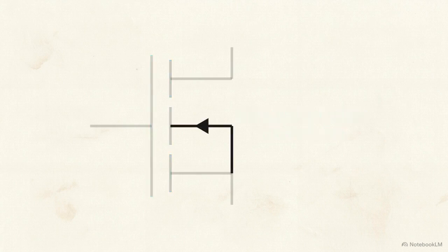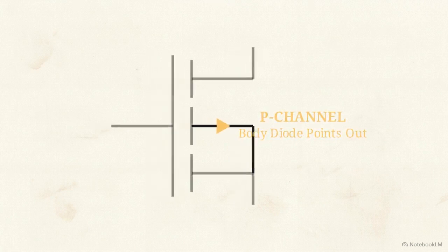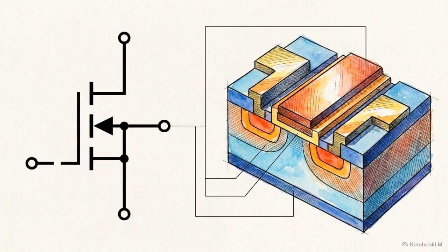Current can flow in either direction when the MOSFET is on, so the arrow doesn't indicate current flow. It's actually the standard primitive symbol for a PN junction, pointing inward to denote an N-channel substrate's intrinsic body diode, and outward to denote a P-channel. The IEEE 315 MOSFET symbol functions as a codified schematic formula, mapping the transistor's underlying physics directly onto the page.